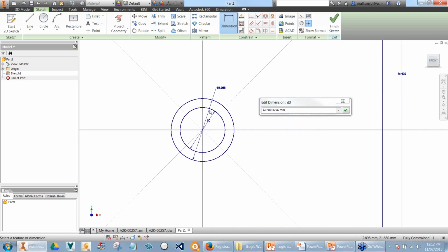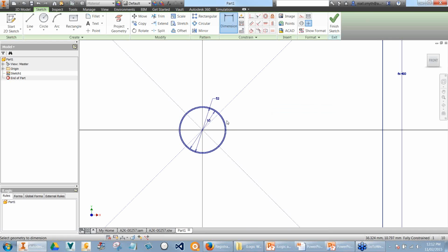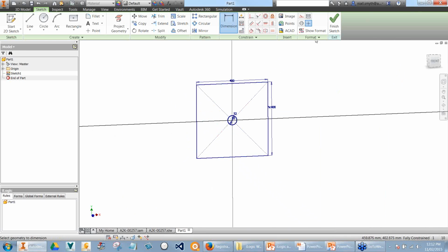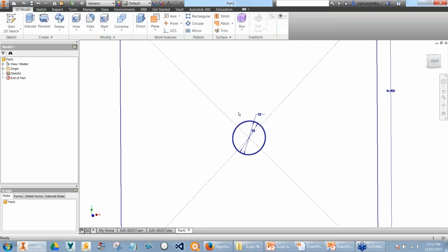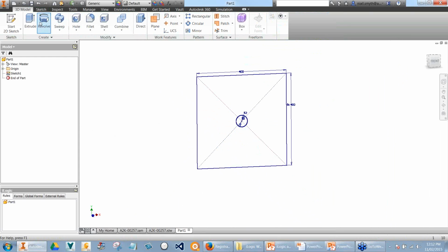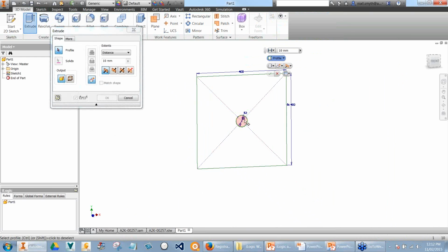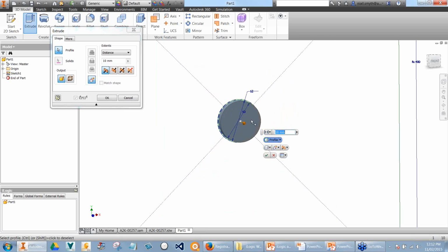Okay, so as we're putting in the outer diameter, so I guess it would be the inner diameter for our hole, what I'll do is call this hole ID, and we'll set that equal to maybe 52 mil. So we've got a 2 mil gap there for clearance. With our very simplified sketch, let's extrude and create these solid bodies.